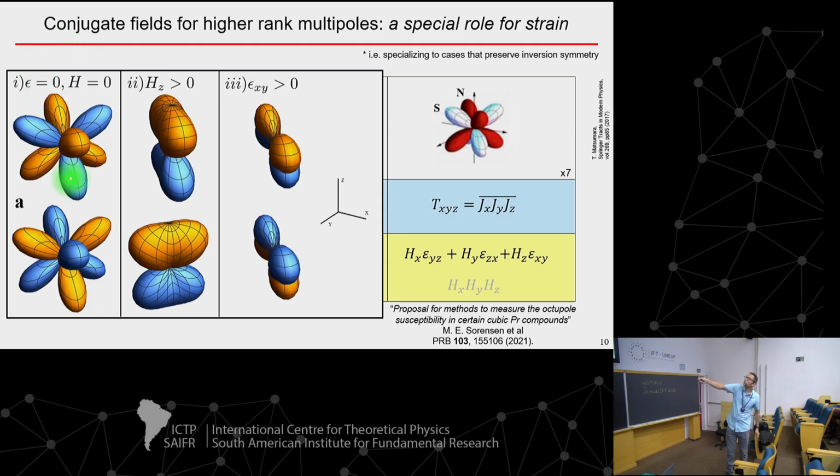That's what this combination is doing. Or I could imagine shearing this, and that's what I'm going to show over here. So if I pull in this direction, I'm going to either induce a dipole up or a dipole down. And again, this is not differentiated in the presence of the shear strain, but when I apply a magnetic field, it will be. Again, that's what that's doing. Right? So this is the intuition behind what group theory is telling you to do. And the point that Elena made very beautifully, you don't know the strength of the coupling parameter in front of that. Group theory isn't going to tell you that. But you've got a pretty good feeling about this using rare earths because of the strong magnetoelastic coupling.